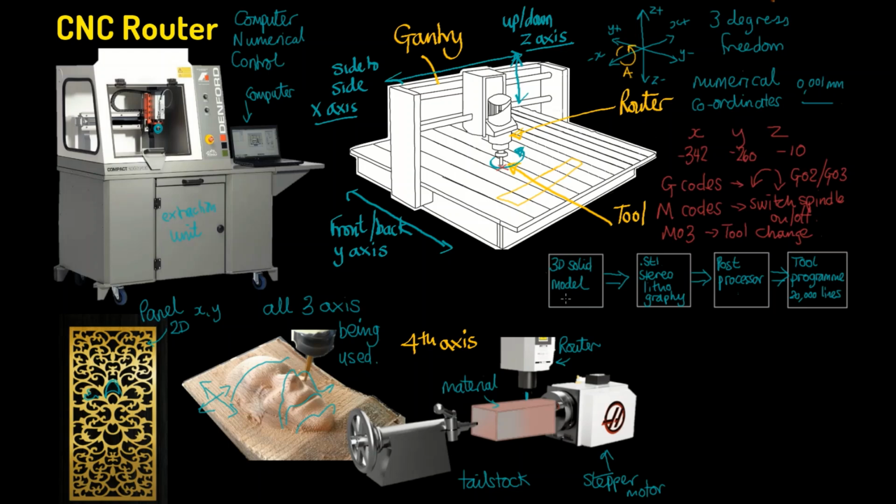We go through the same programming system because the post processor will now include the A axis and will get this material to rotate, as well as the router moving normally from side to side in the X axis. And you only need the Y axis to get to the starting point. As a result, you'll be able to get these profile cuts rather like you can on the wood lathe, which, if you remember, has 360 degrees of symmetry. So you can get some really complicated looking items.